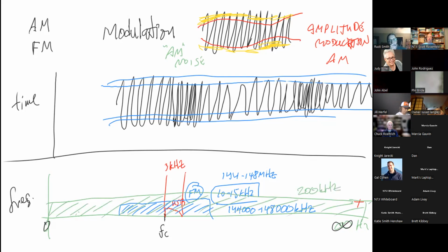The reason that we do that is because there's something called deviation. Deviation determines what your voice does to the frequencies. The deviation is much higher for commercial radio. The reason is that the greater the deviation, the greater the fidelity that you can reproduce. And because you want to be able to hear classical music as opposed to just somebody talking, it uses much higher deviation, which means it takes up a lot more room.